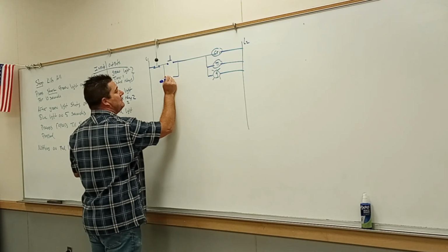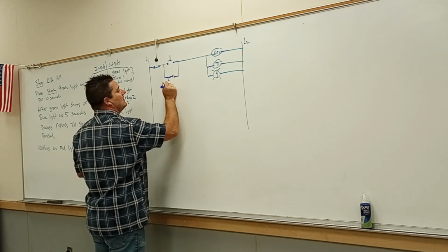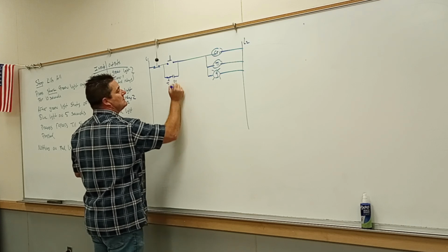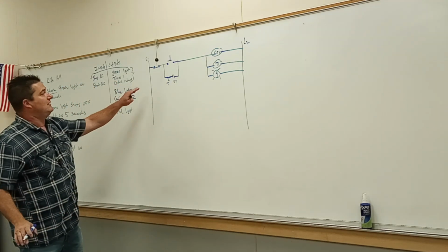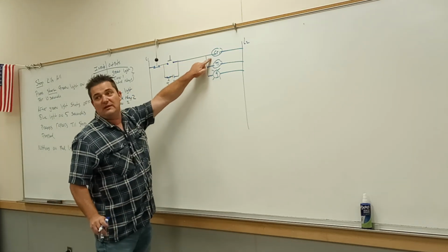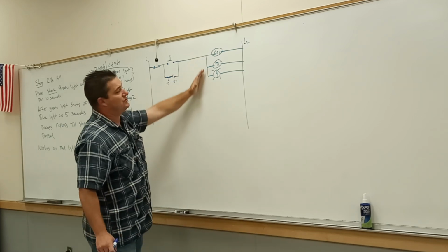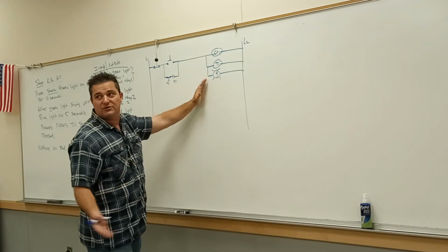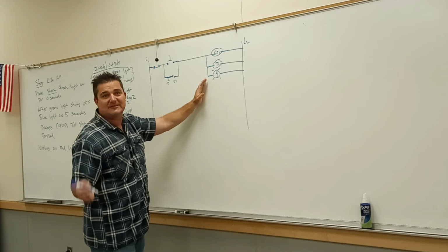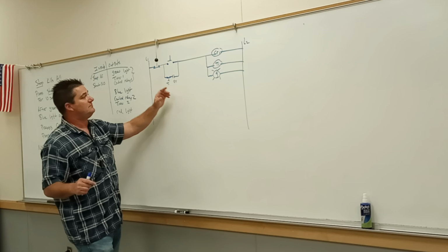Run it through the timers, normally closed contacts, T1, CR1. So now we look at it. When I press start, control relay comes on. That seals your memory. Those are all 3 in parallel. Those are all 3 going to be on at the exact same time as soon as you fire that start button.